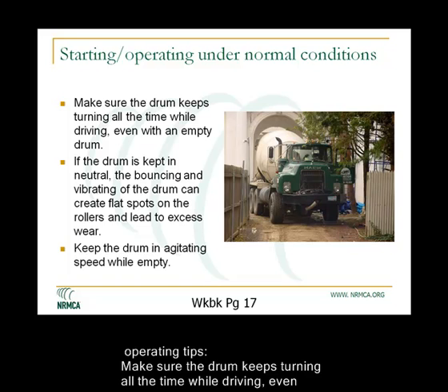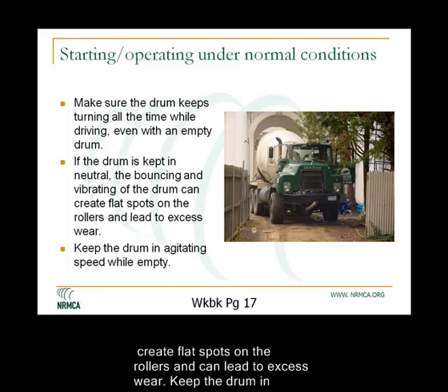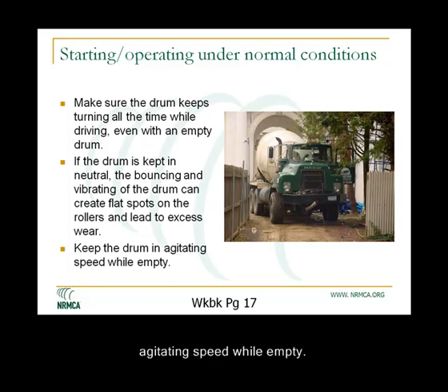Make sure the drum keeps turning all the time while driving, even with an empty drum. If the drum is kept in neutral, the bouncing and the vibrating of the drum can create flat spots on the rollers and lead to excess wear. Keep the drum in agitating speed while empty.